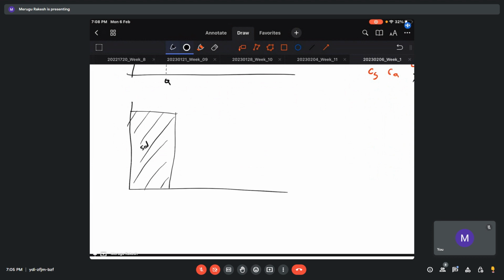so this is the solid that is already formed, and I have this spike coming up. Now this is the actual cooling rate that I should follow, which is exactly what happens in pure metals. But generally it happens in this range for alloys. So there is a region, this is the undercooled region.